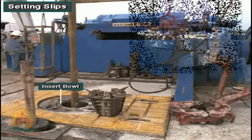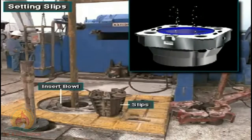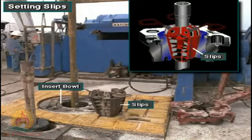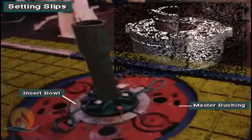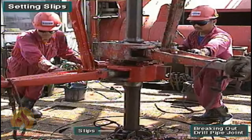Manufacturers taper the inside of the insert bowl. They taper it to match the taper of the back of the slips. The slips grip the drill string and suspend it inside the insert bowl. The insert bowl fits inside the rotary table's master bushing. Suspending the drill string in this manner allows crew members to disconnect the Kelly or top drive and break out joints of drill pipe.